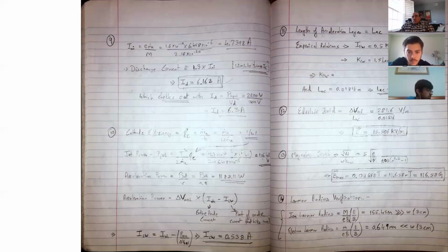This can be computed by combining two different equations. One is, we know that the thrust is m dot v, right? And we also know that the jet power is basically half m dot v squared, because it's the kinetic energy of the ions coming out. So half m v squared is the kinetic energy, and half m dot v squared would be the power.